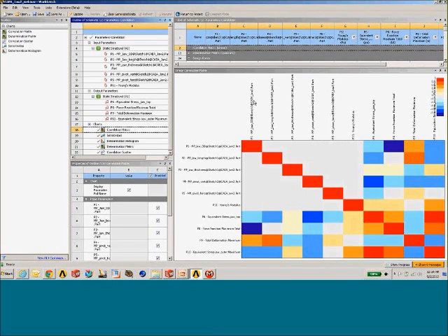So let's take a look at the first column here for parameter number 1, and take a look at the output response down at the bottom of the column. We can see that we have a very strong correlation between a change in the jaw OD, parameter 1, and the reaction force that's required. So that's a parameter that we want to hang on to in our DOE. Moving over to parameter 2, we have a fairly moderate correlation between the equivalent stress, the total deformation, and the jaw length. Moving over to parameter 3, it looks like we have a very weak correlation.